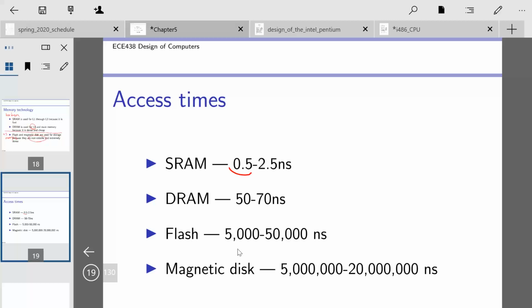So I'm sorry, for your SRAM, your level 1 instruction cache and data cache both would have to run at a half a nanosecond or faster. Okay. Now, if you want a larger level 1 cache, then you're going to have to pipeline it, and that's where you start getting into your super pipelining, which would be like your 8-stage RISC processor, like the R4000, where they went ahead and split the instruction and data caches up into two stages. Actually, technically, it's 3 stages.